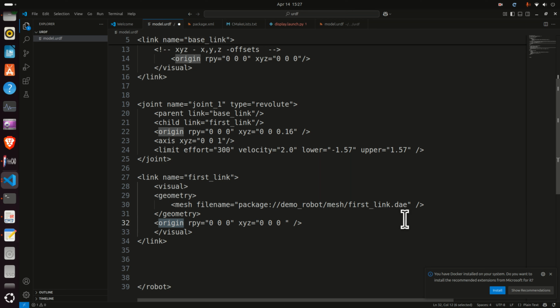This is actually not the center of the link when you import the CAD geometry. This is actually the coordinate system. That's precisely this coordinate system defined over here. That is the coordinate system of the joint. This is just a convention when importing the CAD files. If you manually define your geometry over here, such as using boxes or using cylinders, then this coordinate system is located at the center of the link. To repeat, this coordinate system over here, and its offsets are 0, 0, 0, is precisely the coordinate system of this joint over here. Okay, so let's save this.